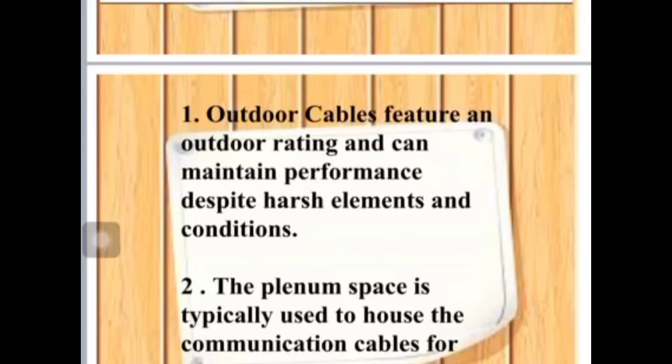Underground cables can be installed when they sit inside a conduit. This added protection allows cables to sit underground, and when exposed to these elements, this cable has water blocking filler of polymer gel that stops water infiltration in underground burial cables.